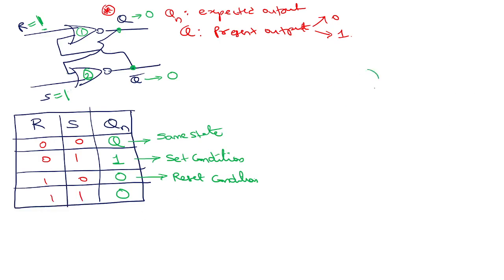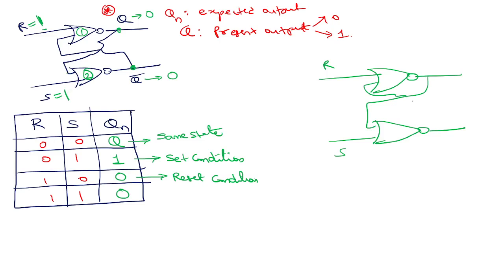Don't skip anything. Technically you tell me, logically you tell me, let's say these two nodes are like this. Forget about Q and Q bar, I didn't write. I wrote some A, I wrote some B, or you can write monkey, donkey, also fine, no problem, output side. Now, logically tell me, if I write R equal to 1, S equal to 1, is something wrong with this?